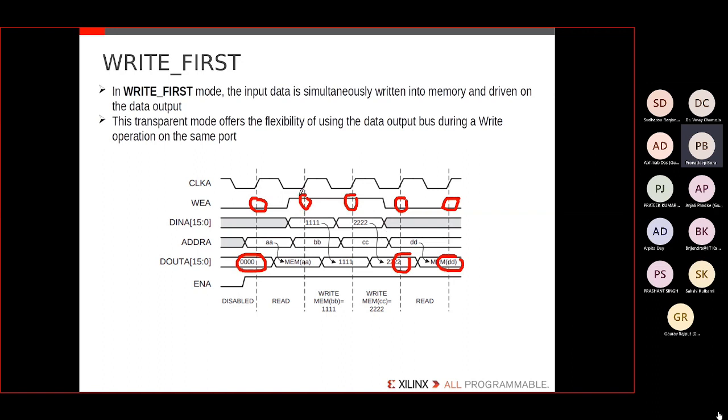So whenever I'm doing a write, you can see I'm using the write enable signal. That means write enable is high, and I'm sending this particular data. What is happening? At this particular address, this data is written. The data has been written. But at that instant only, after some intrinsic delay, that is the internal gate delays, I'm getting the output at that moment only. So this is the advantage.